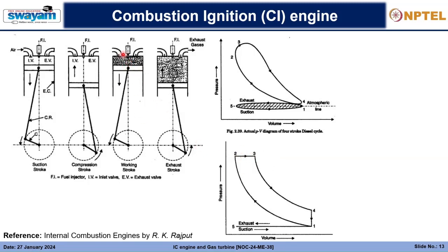The reason behind this is that when the fuel is vaporized into the gaseous components, the increase in the volume with time is compensated by the volume created when the piston is moving downwards. So the net pressure, which should have increased, is remaining constant because the volume is compensated by the piston moving down. So the 2 to 3 is a constant pressure process. And this cycle that we have is the diesel cycle, and this diesel cycle will be followed for a compression ignition engine.